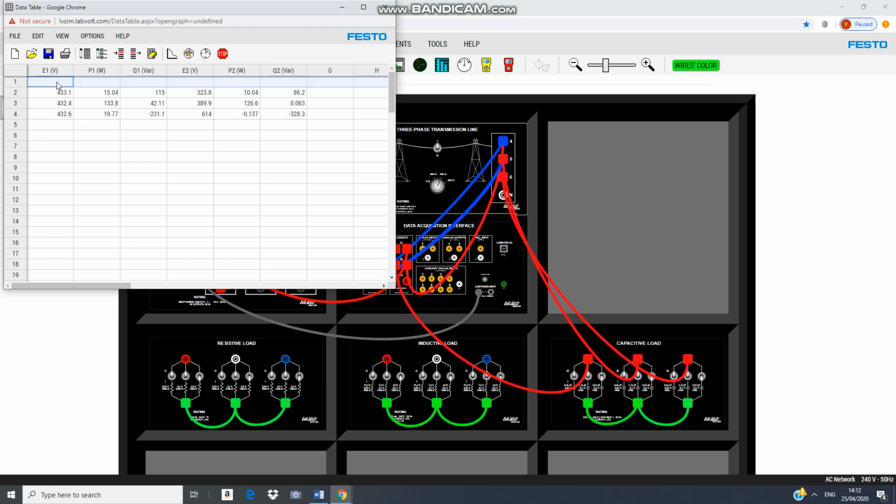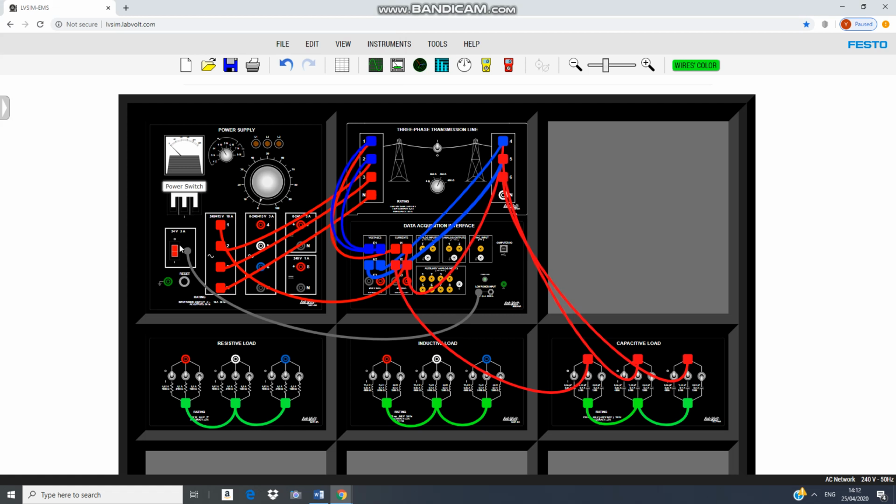So we start with open circuit. We see how to do open circuit. Switch off the system. So for open circuit we disconnect the load, delete this wire and these 2 wires. For open circuit we just need to measure the voltage between this point and this point, nothing else.